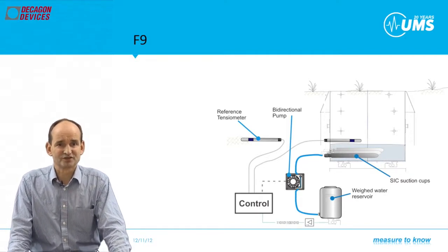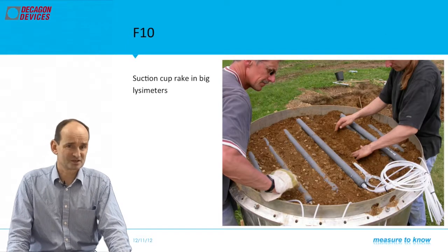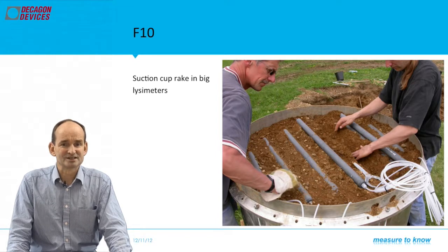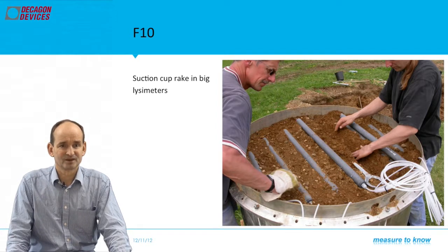The active surface of the porous suction cups or the suction cup rake is half of the lysimeter surface. In the Wagner project 2004, we tested if this is enough to even cover highest infiltration rates, which was the case, and no free drainage got below the suction cups to the free drainage outlet, which was provided to be on the safe side.